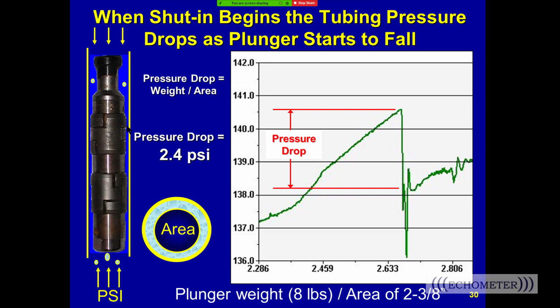Don't use CO2, because if you do a test for like 4 hours, even though the O-rings are designed for CO2 gas, after 4 hours the O-rings will get CO2 dissolved in them, and then when you release the pressure of the gas gun to fire the shot, the O-rings will fizz as the CO2 comes out and they'll pop. So you should always use nitrogen gas to charge the gas gun to a pressure greater than the well pressure.